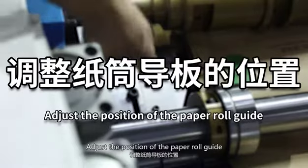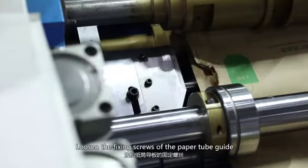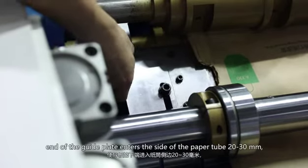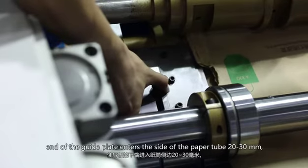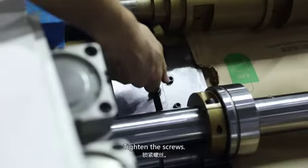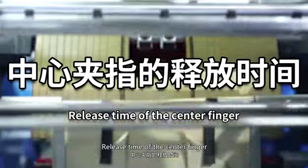Adjust the position of the paper roll guide. Loosen the fixing screws of the paper tube guide. Move the guide plate along the axis so that the lower end of the guide plate enters the side of the paper tube 20 to 30 mm, and the upper end of the guide plate is about 3 mm away from the fingertip of the drum machine. Tighten the screws.